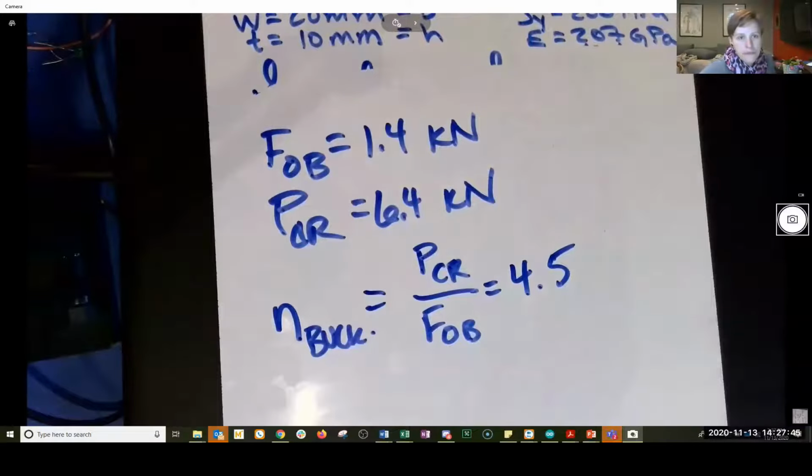That's fine. Never mind. Yeah, so what would be different for in-plane buckling? We already talked about how inertia would be different because base and height change. They swap. What else is different? The end conditions would be different? Yes, so C goes from 1.2 to 1 because it's pinned on both ends, so buckling becomes easier.